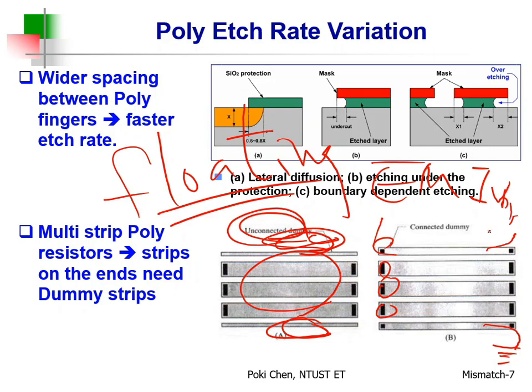I think I don't care. Right? Again, it means what? The so-called clean sources cannot be used as your VDD or ground for operation. The VDD and ground for your circuit needs to be different from the clean sources. Okay? For grounding, blah, blah, blah. All right. That is what I recommend you to do.